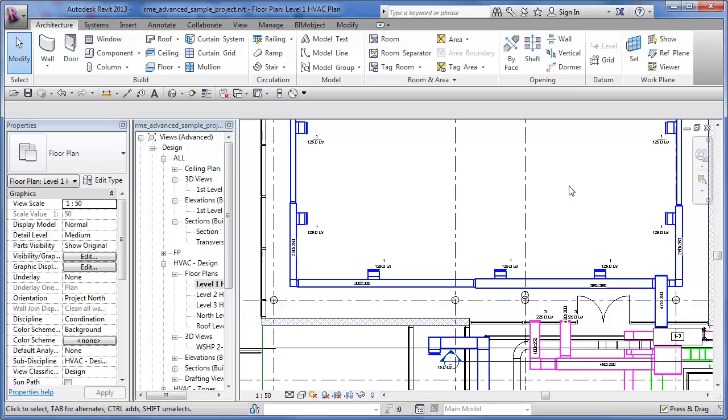And the next little thing we're going to talk about with our Revit 2013 with dimensions is the equal or equality parameter that we can use to constrain objects. So here you can see we have these diffusers or air terminals. And what I'm going to do is put an equal spacing parameter in my dimension across here, and we'll watch those respace.